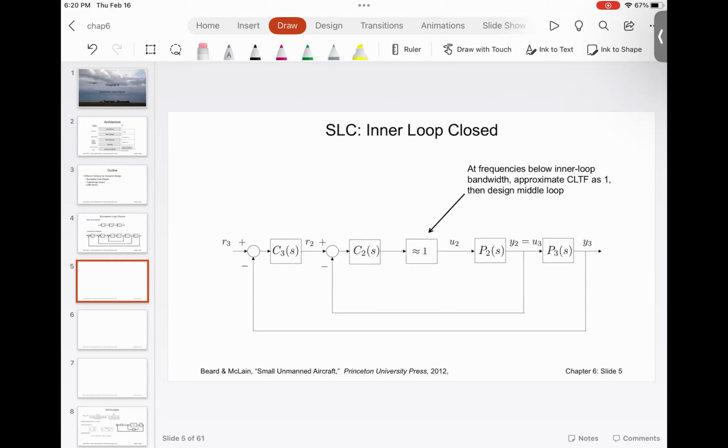And what we did in this nonlinear equation, somehow we linearized part of that nonlinear equation. And part of that equation could not be linearized. We treated that as a disturbance. And we designed a block diagram wherein the external control input is able to overcome the disturbance and also control the system dynamics.